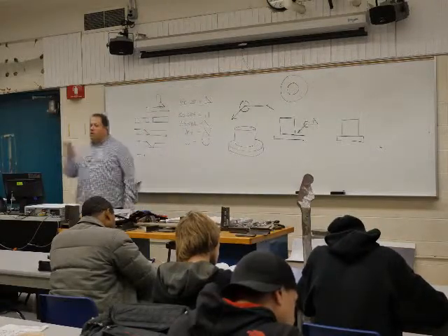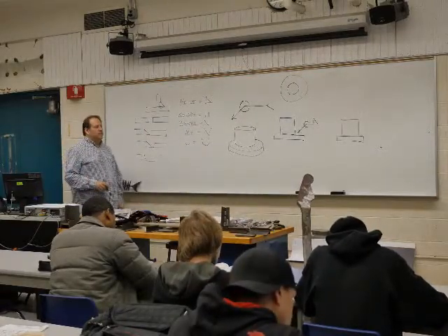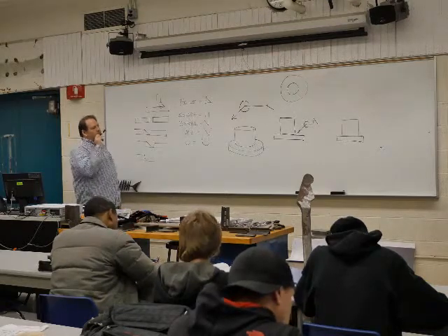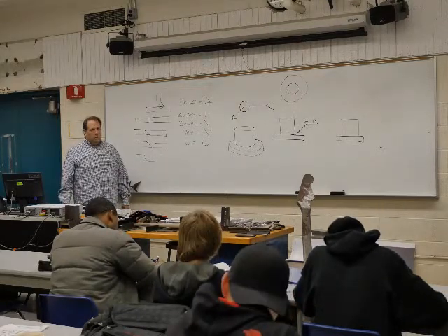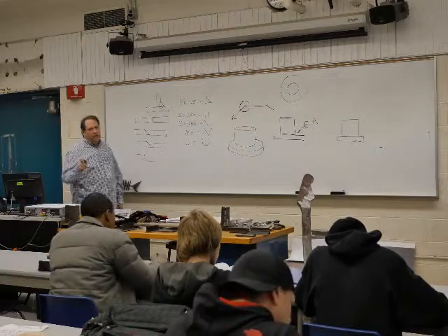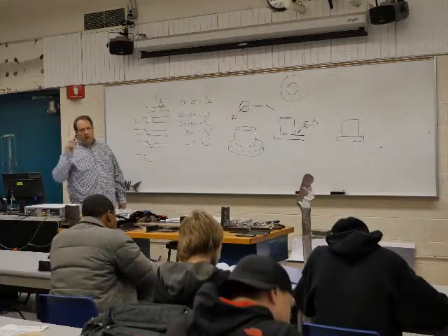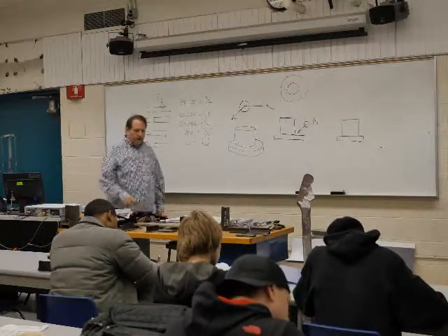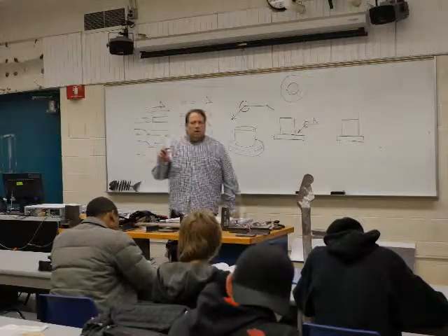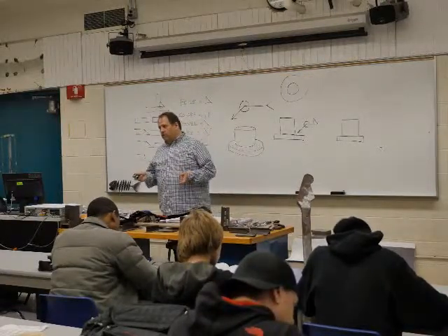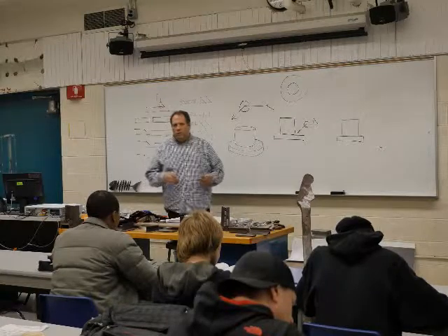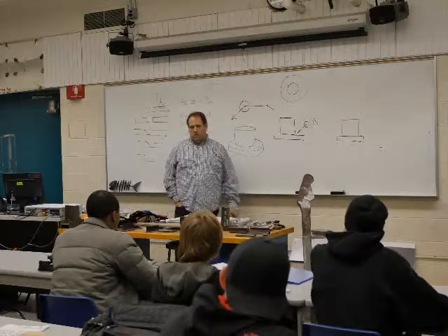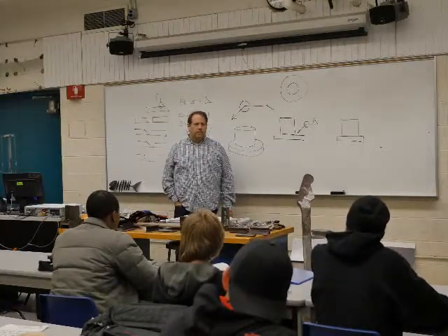Now, the important thing here is this. We said we have an all-around symbol, a weld all around. We also have a fillet weld, and we have a fillet weld on a certain side of the reference line. This is where it could get a little confusing, except for this. Which way do we read? Left or right? Yeah.